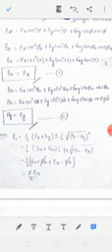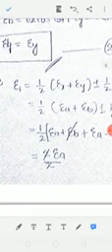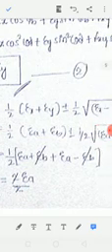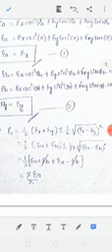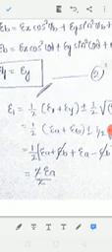So no need to write the whole complete equation. You can remove that. So I can write epsilon 1 and 2 equal to 1 by 2 epsilon x plus epsilon y plus or minus 1 by 2 under root epsilon x minus epsilon y square. So this is also I can write as epsilon 1 and 2, right? Now maximum principal strain and minimum principal strain. Now epsilon x also I can write epsilon a, epsilon y also I can write epsilon b, plus or minus under root epsilon a minus epsilon b. So I can replace epsilon x by epsilon a and epsilon y by epsilon b. Now you can simplify.